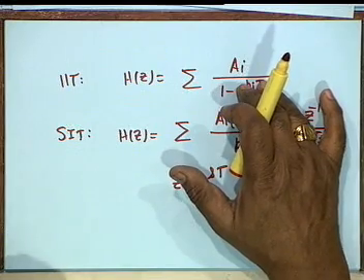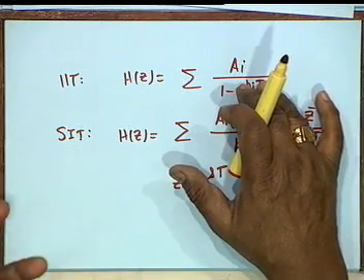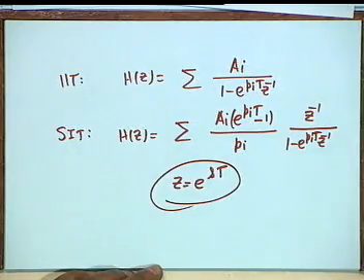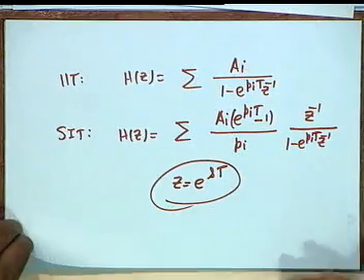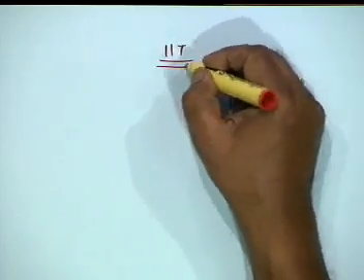It's a very fine difference, but you should be able to answer why, using the same transformation, the two transfer functions are different. One creates a zero at infinity, the other does not, and that is the difference. Okay, let's go back. Similarly, you could get a ramp invariant transformation, or any other function invariant transformation, but impulse invariant transformation is generally used in practice.